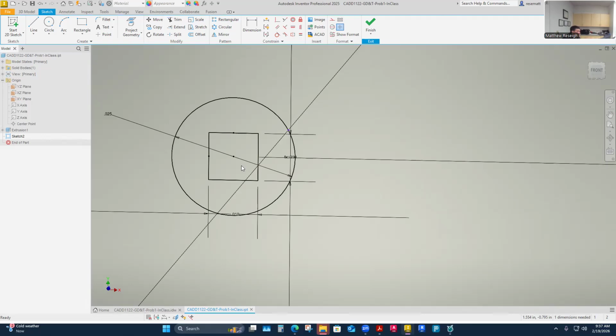Your tolerance block kind of gives you that. You see that at three decimal places, that's 5 thousandths of tolerance. That's a pretty high level of control. Anything like 1 or 2 thousandths, you're expressing extreme, really fine control. I think a machinist might call it a general tolerance. I was watching some videos, and they say maybe 14 thousandths is their medium general tolerance. So really our tolerance zone is 25 thousandths, which is quite a coarse tolerance zone.